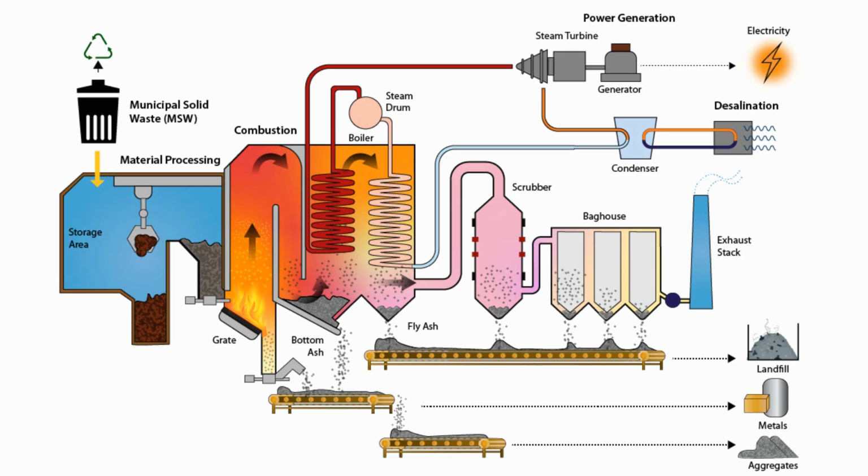Generally though, a waste-to-energy boiler will be larger in terms of dimensions than a coal-fired power boiler. Not only that, but the exhaust gas cleaning system will be different compared to a coal-fired power plant. Other than that, the steam systems, the water systems, the electrical systems, they're going to be very similar to what we've seen in a coal-fired power system. Only the type of fuel burnt, the dimensions of the boiler, and maybe the designs of the tubes, and the exhaust gas cleaning systems are going to be different from what we saw with our coal-fired power plant.